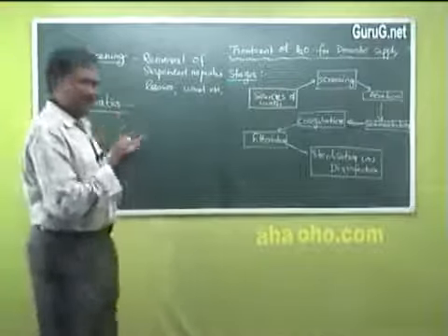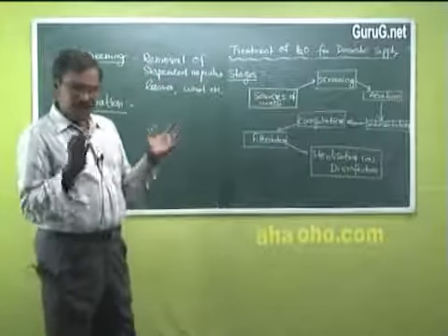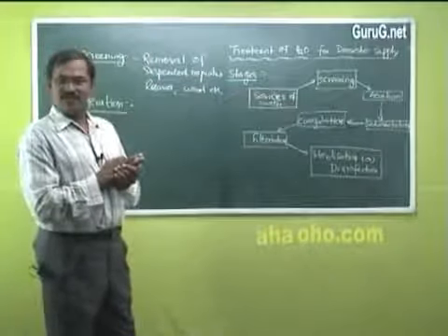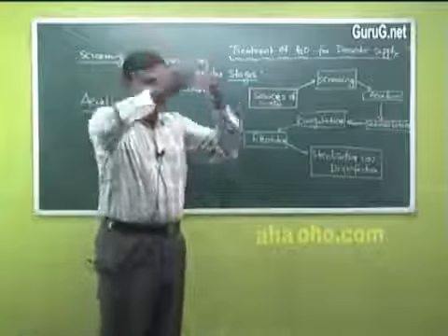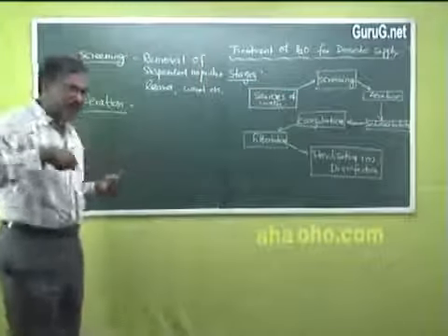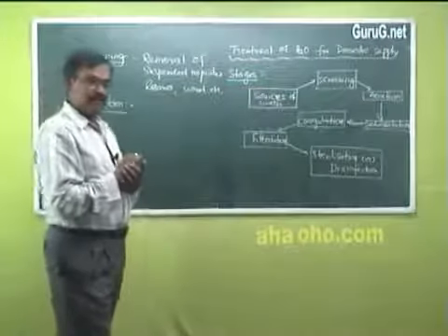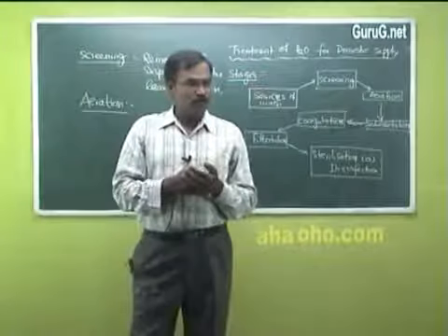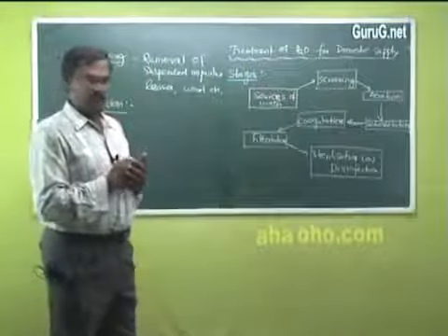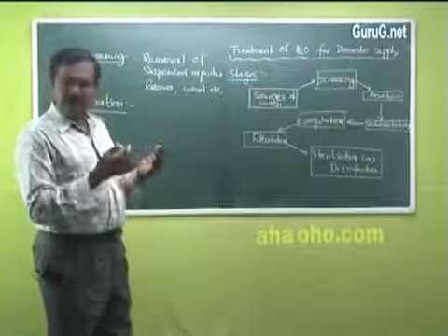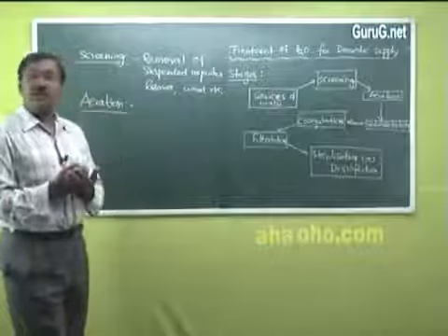It is very simple. The name itself explains the meaning. Aeration is nothing but mixing the water with air, that's all. Air is bubbled through it, or water is allowed to fall from some height. So water is mixed with air. When water is mixed with air, what will happen? Some dissolved gases like CO2 and other poisonous gases may be swept out. It will come out, especially hydrogen sulfide, carbon dioxide, ammonia, or any other dissolved gases.